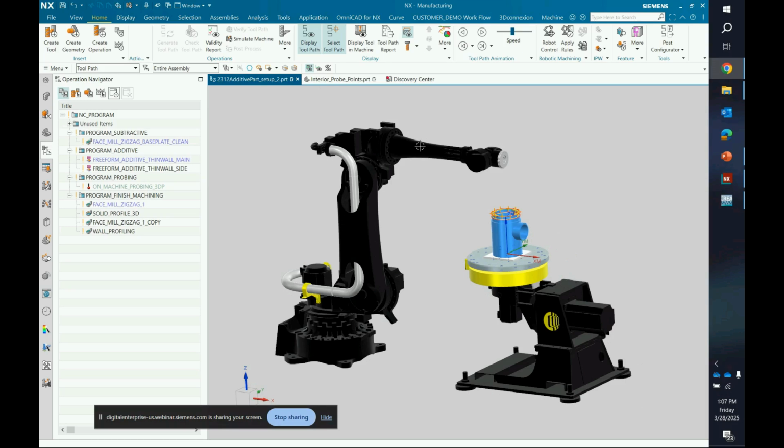I think there's an open question. I don't know if it got answered, about where you teach robot configuration. When you strap a Numeric controller onto a robot, now you're looking at it from a CNC perspective and out of a robot pendant, robot controller perspective. What I mean is we're not teaching. You can teach points, you can teach positions, but we're not exactly teaching points and configurations like you would with a typical production robot doing the same thing over and over.